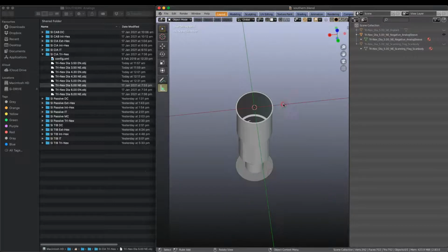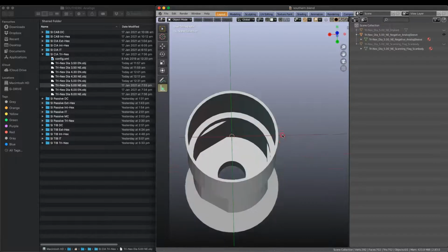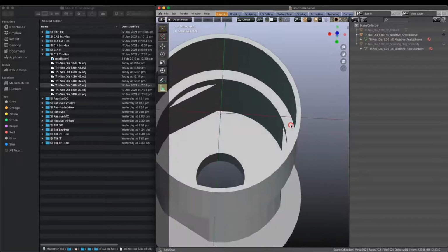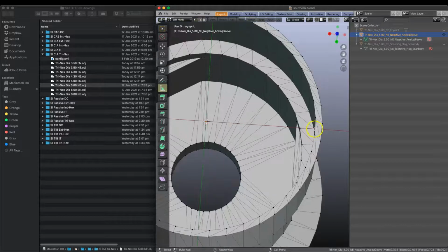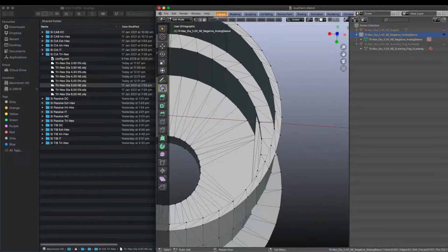If we measure this little ledge that they've provided here, we will see that in edit mode, tab into edit mode, and I'll be able just to take a measuring ruler here, and from the one side to the other we'll get to maybe 0.15. I'm going to be adding, say, 0.55 onto that, and then we'll have our wall thickness of 0.7.